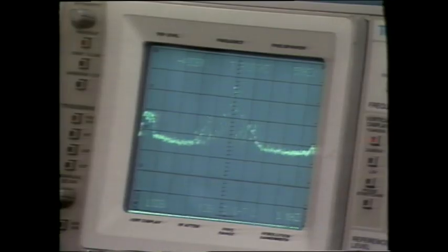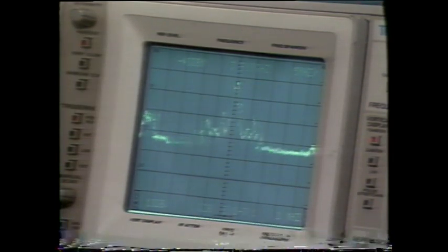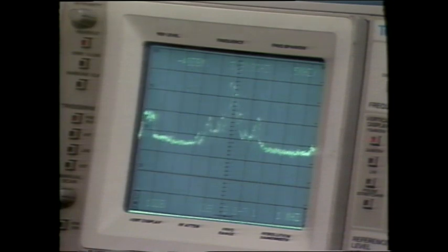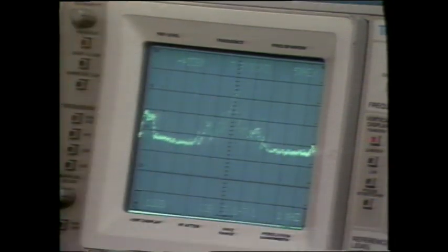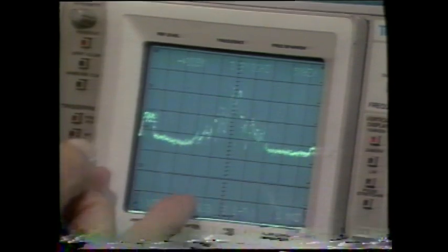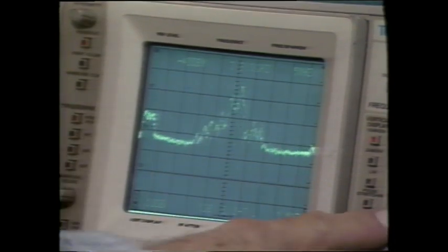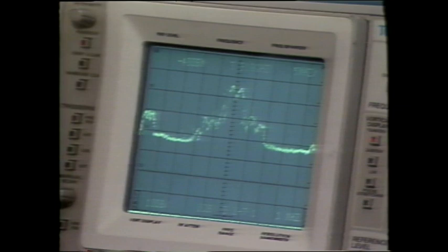Archie Brush also showed us how frequency deviation, or as satellite engineers call it, spectrum occupancy measurements are made. Well, 492 is practically the only instrument we can easily make the measurement on at this end. And the way we do it is center the video in this case. Somebody is sending video on this transponder, and depress the maximum hold button, and you'll see what's happening is it's remembering everything that went by it.